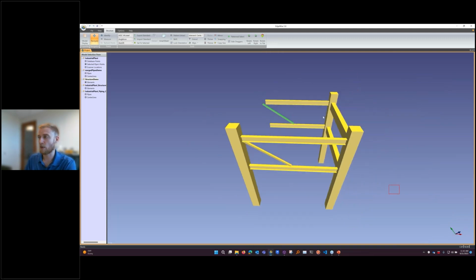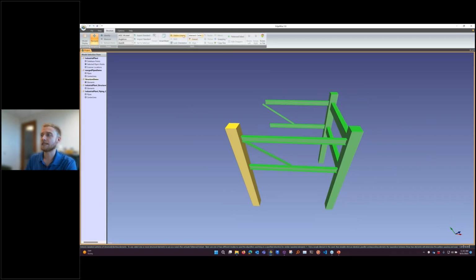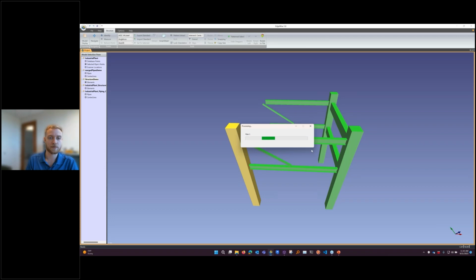And the cool thing is I can grab all of this and do the same thing, but instead of going across, I'm going to say the column from right to left, and it's going to go through and look for each one of these individual pieces of steel and concrete that we've extracted and try and fit those to the point cloud based on that pattern, and it'll go until it can't find any more structure. With this demo, we're going to extract pretty much everything. But this can be really nice where there is a lot of repetition in structure, but we're accounting for the fact that things will be a little bit twisted or maybe 1 or 2 inches off from that exact array, and we're just fitting stuff to the point cloud, and that's the key value there.